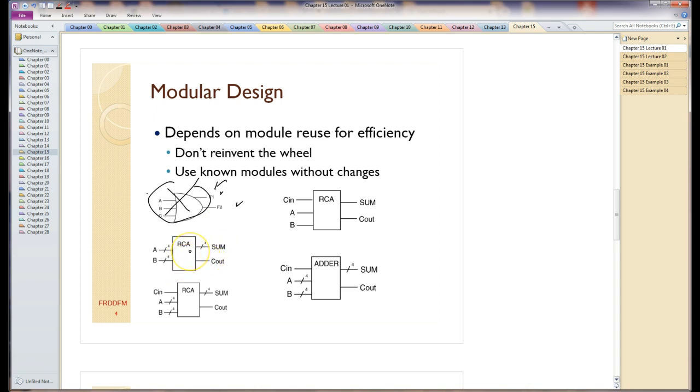There's a question of whether it needs a carry in or not. So here's the same circuit with a carry-in, but this circuit is okay. It's assuming this circuit doesn't have a carry-in, which may be what you want or not want. Certainly if you need a carry-in, it has to be there. This circuit actually lists the carry-in. These are both valid circuits. They reflect what I know about ripple carry adders.